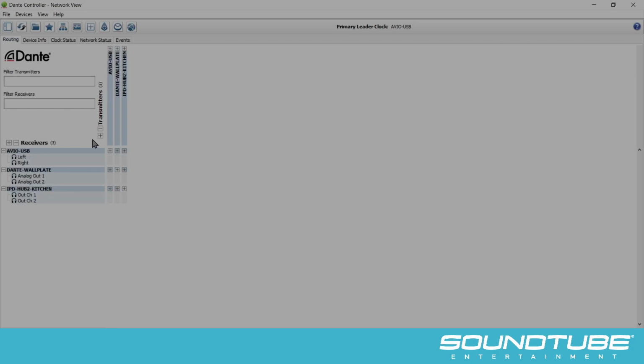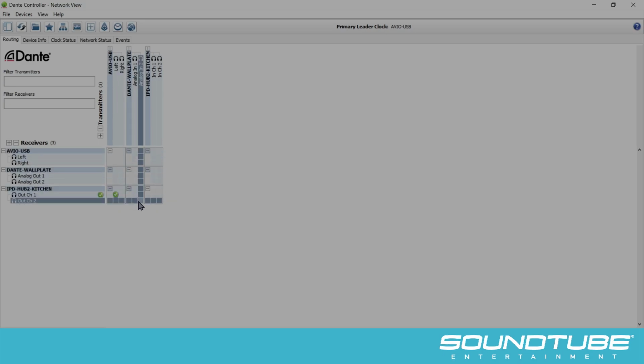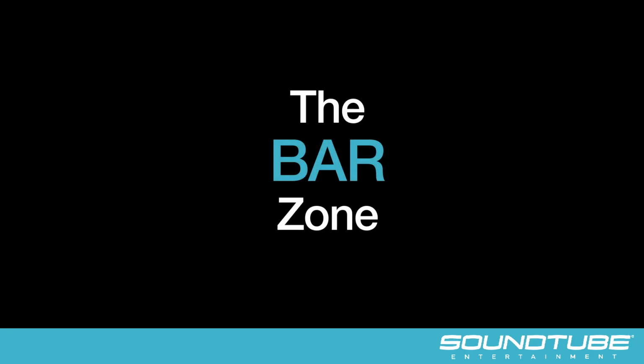We will be sending audio directly from the laptop through the Avio USB device to our IPD-Hub 2's Receive Channel 1, marked Out Channel 1. Our paging audio will come from the Dante wall plate directly to the Hub 2's Out Channel 2. We're now ready to move on to the bar zone.